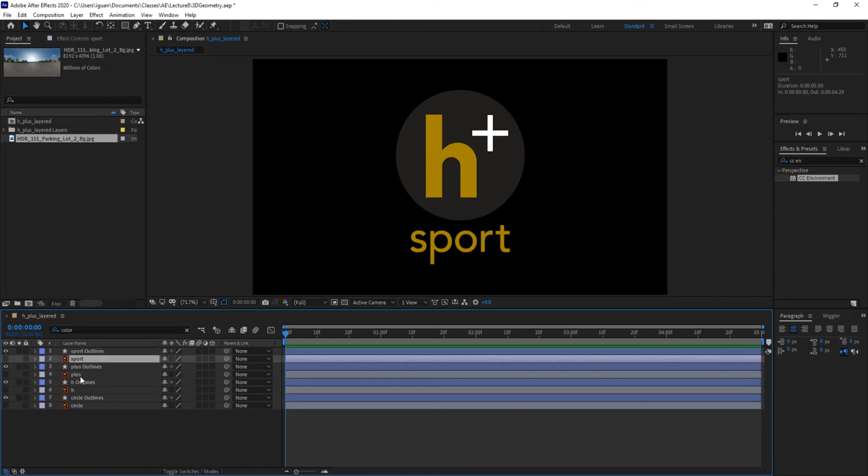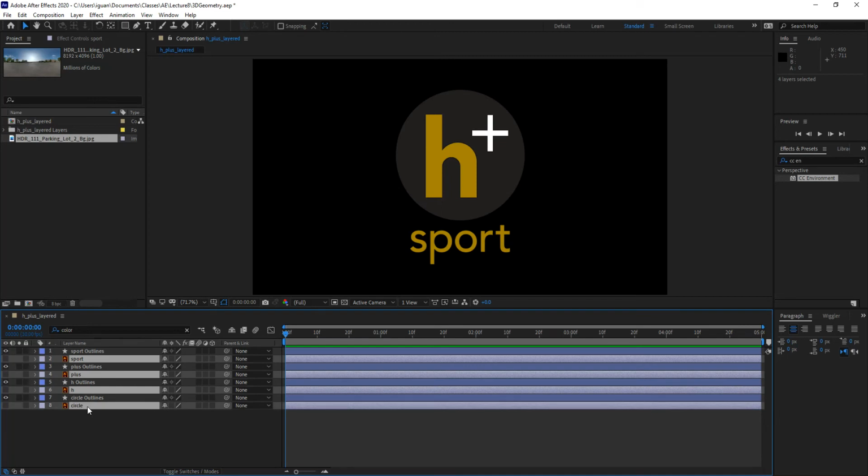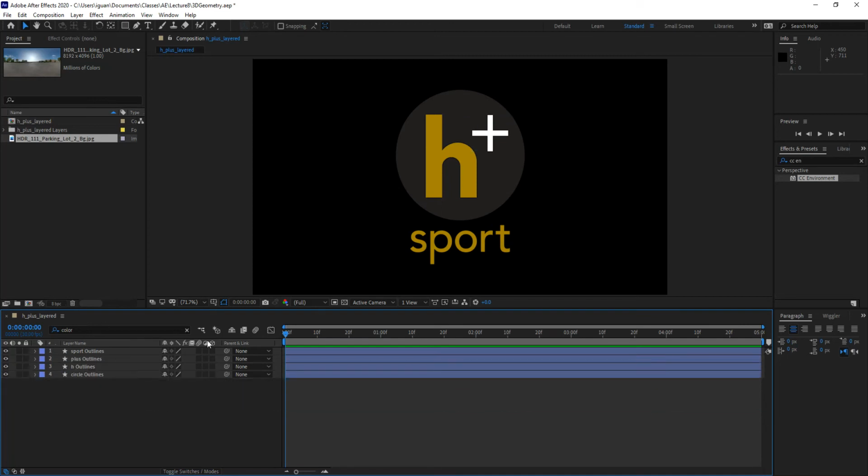So what I want to do at this point is select all the Illustrator layers and delete them. I only needed them to bring the artwork into After Effects. Now with that done, I want to make sure that I can turn them into 3D layers and create 3D geometry with them. But before we do that, I want to do a couple of changes. I want to create a hole in that circle where that H happens to be. So how do I use that path information to cut the path from the previous path, from the circle path?